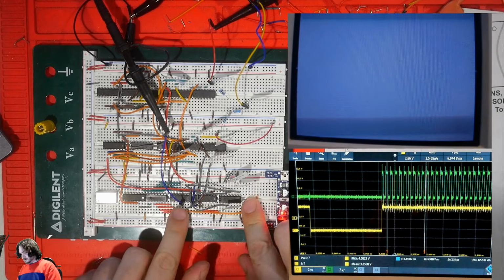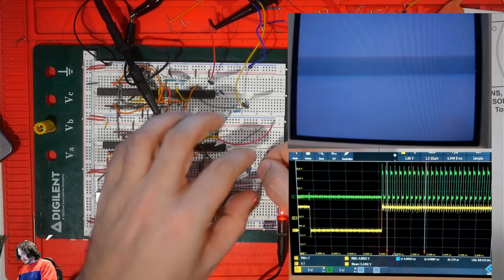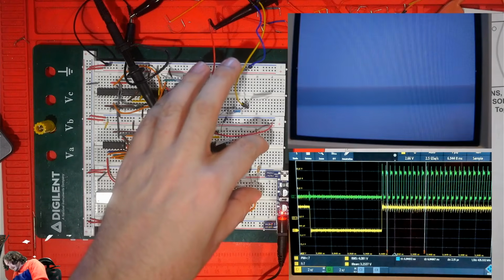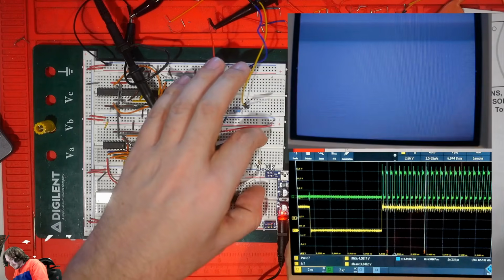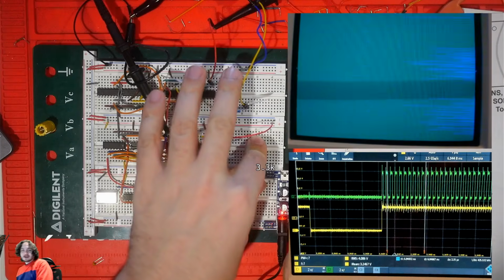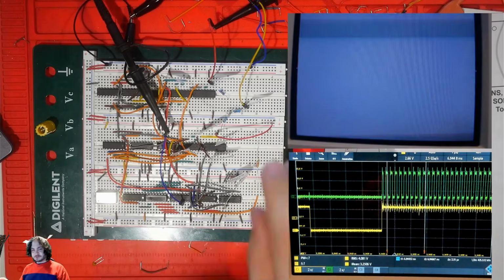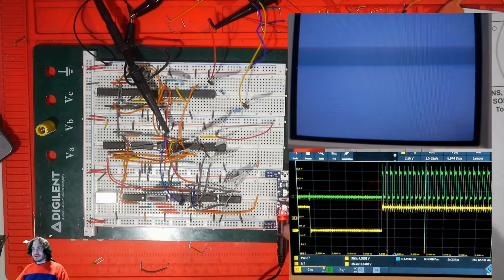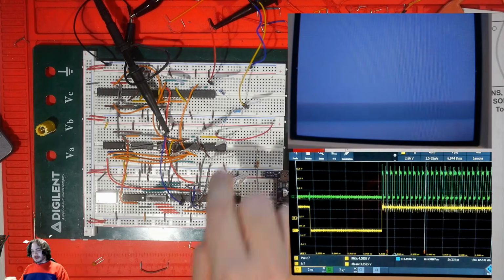Up there. This resistor is also acting as a jumper. What we want, though, is for only this high frequency to be carried over. If we simply mix this in with the resistor, the average DC value of this signal is going to pull on the output.